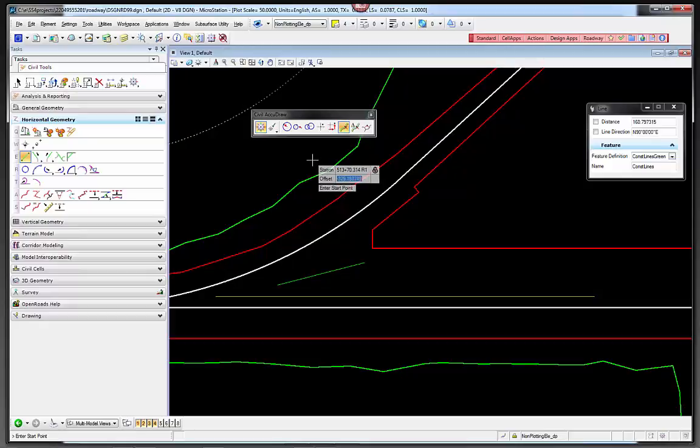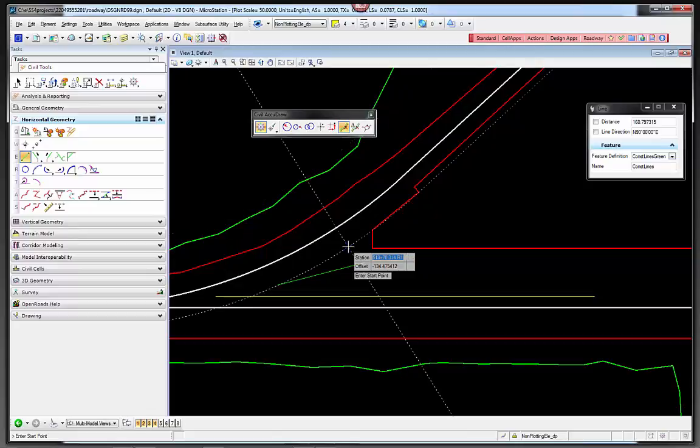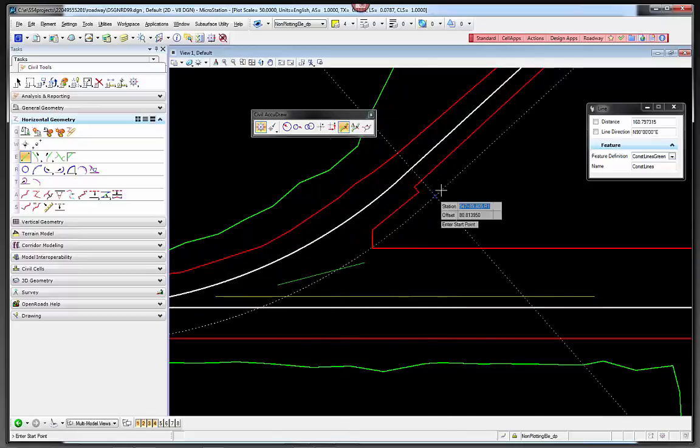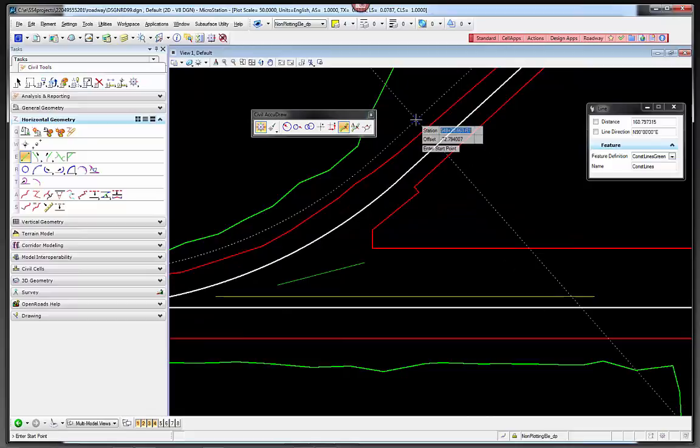Whenever you're doing the station offset, you want to make sure that you key in the O shortcut when you're in the offset field. So if I'm toggled to station, if I hit O, notice that just the value O actually gets keyed in there. If I tab to the offset and hit O, it allows me to select a reference line. And now I'm tracking, and I want to unlock that. So you hit the N key to unlock it. So now I'm tracking off of this alignment here.